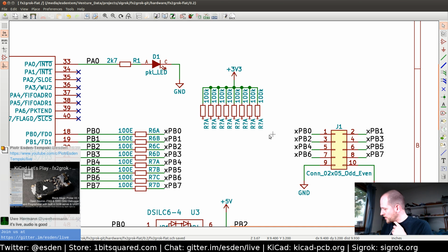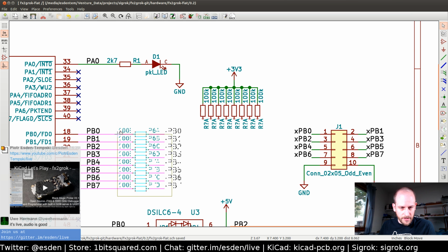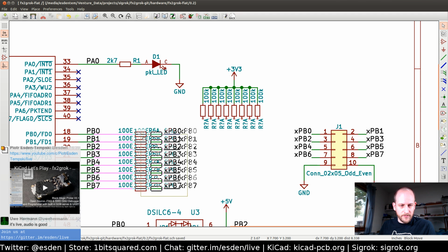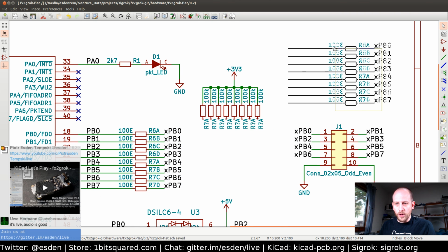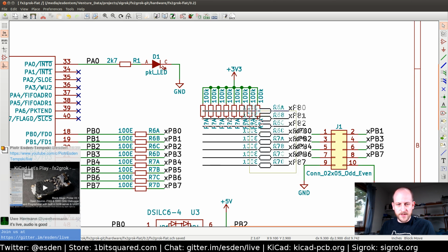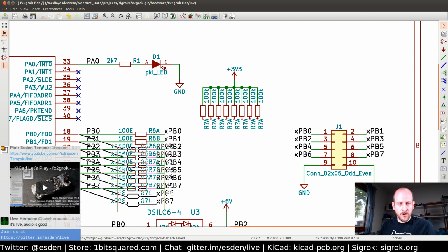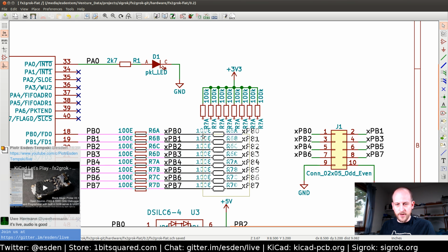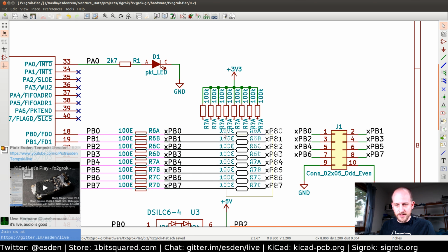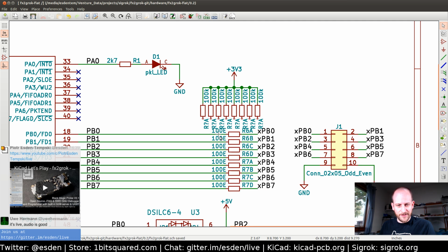Should we pull it up before or after the resistors? So in this schematic, it's after the resistors, or whichever direction you're looking at it. Oh, so the interesting thing is, look, if I just drag it, it will pull off all the traces. What you do, you press tab, and this will keep the components attached to the schematic. That's very useful to know. I did not know that at the beginning. It was quite annoying. So there we go.